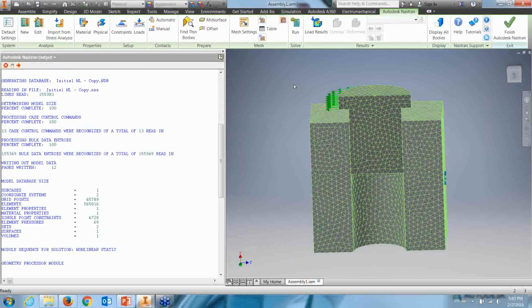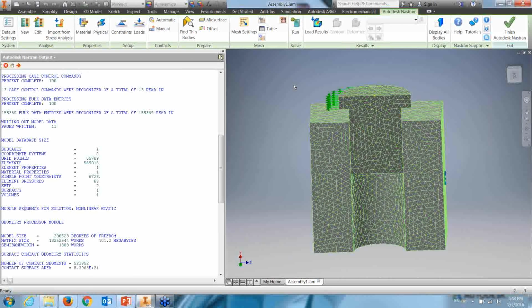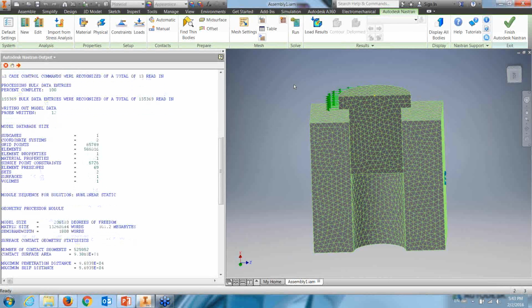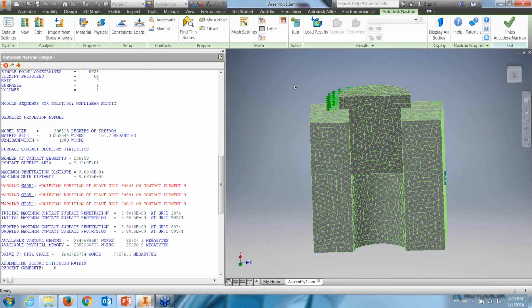And again, the stiffness due to the stabilization is going to be cut in half for each increment, but it's still important to watch. So I ran one of these models earlier, and it had a strain energy of something like 65%. It's not a good value to have. You want it at least 1 or less. Again, it's engineering guidance, or engineering wisdom, as to what values you should use, or what value is low enough for you to have no influence on the model.